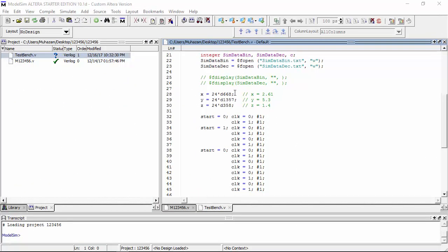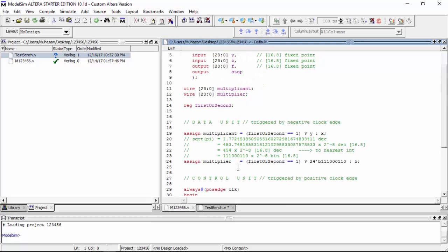Now we can put $display lines at the point where we want to read the output. We need to decide what we want to print. Based on what we have done so far in our formula module, we only coded until the first two multiplexers. So let us probe to see if the two multiplexers give the proper output to the multiplicand wire and multiplier wire.